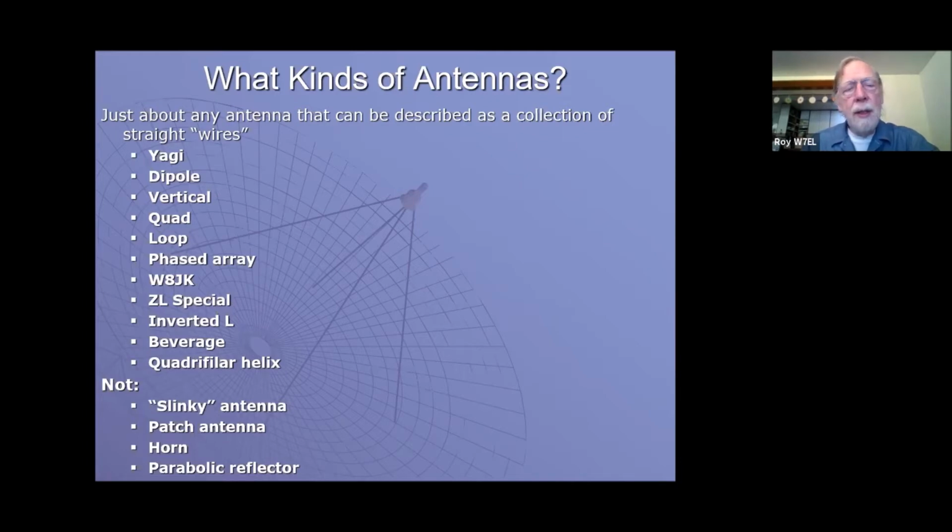Those are pretty easy to calculate. What they're really interested in is the side lobes and the minor lobes. And the wire grid model being an imperfect model of the parabolic reflector, you'll probably not get really good, realistic results of the more subtle features of the pattern from EZNEC.